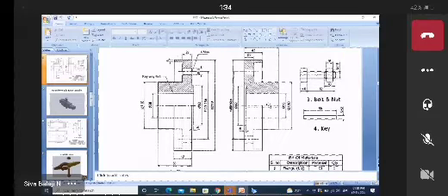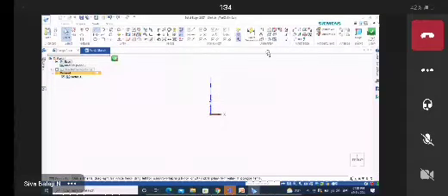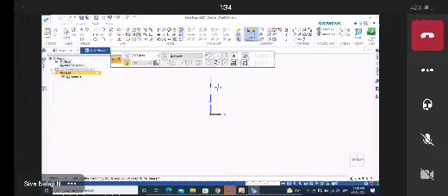First, consider this a coordinate system and draw one line here. 110 mm is given, so you can draw 55 mm here. You can select the line command, draw a 55 length, and give the dimension 55 mm for this length. You can check it in the 2D diagram.